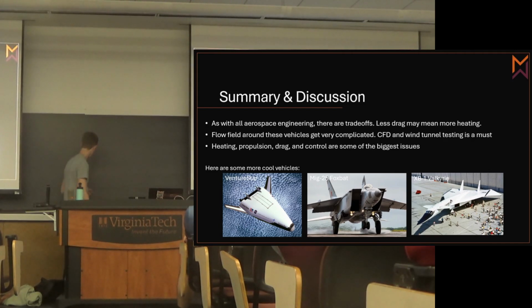So if I take normal oxygen or even just nitrogen, and I put it into here and I expand it, and I put it into a straight wind tunnel, I get problems because the temperature is so low that the nitrogen starts to liquefy. So the only way to combat that is by heating this guy up with a heater, but then your pressure's already low.